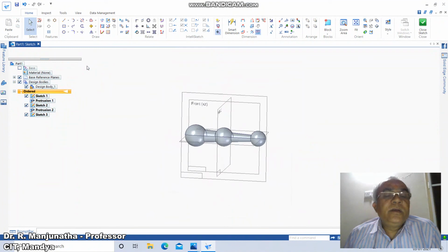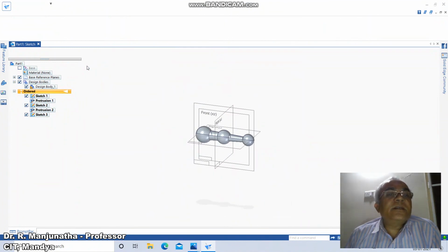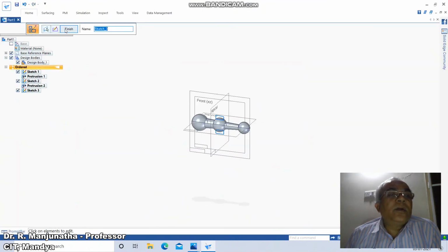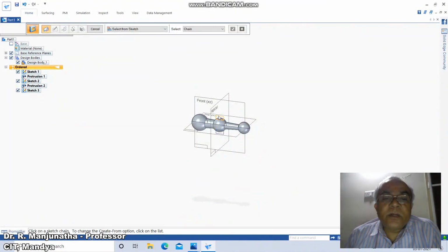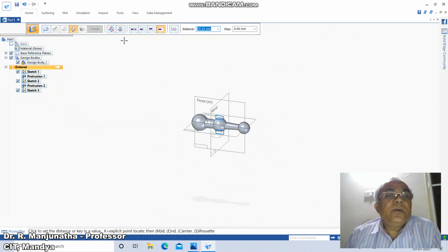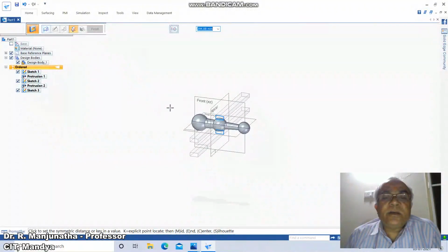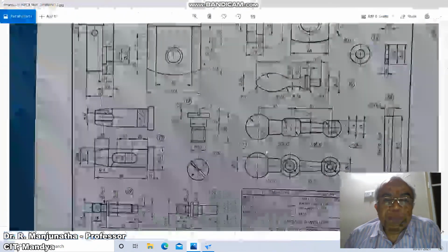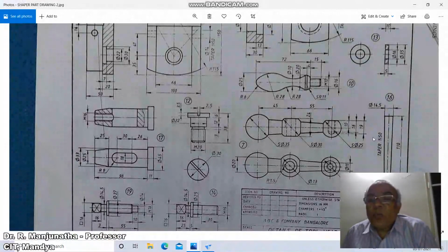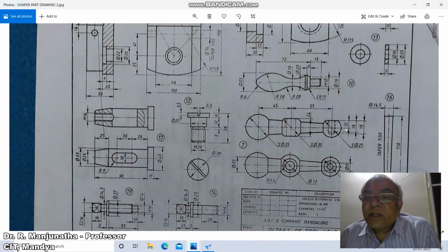Then go to finish sketch, click on home, click on cut. So click on this and click on this, accept it, go to symmetric extent on either side and cut it. So once you get this, now we'll go for the last one, wherein we need to create the distance from 10.